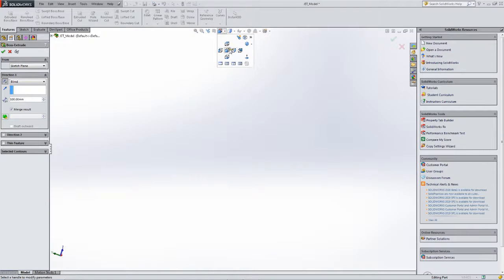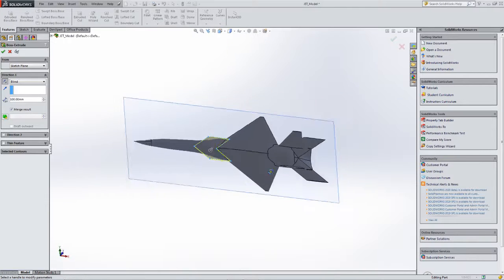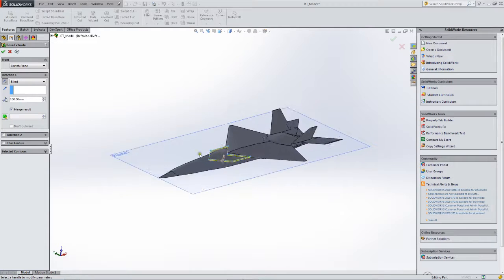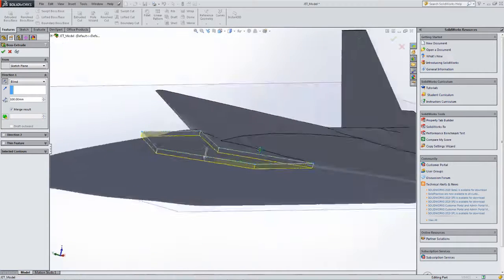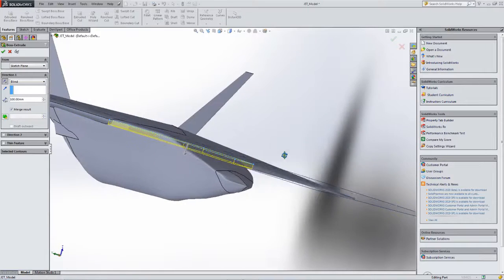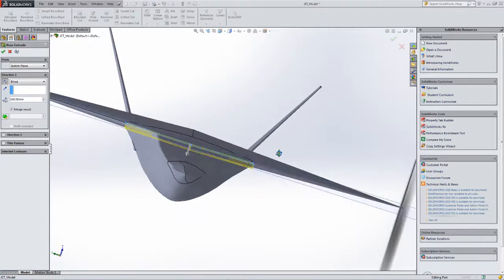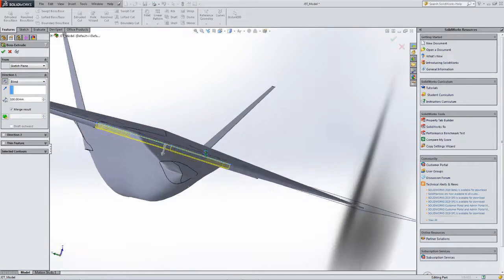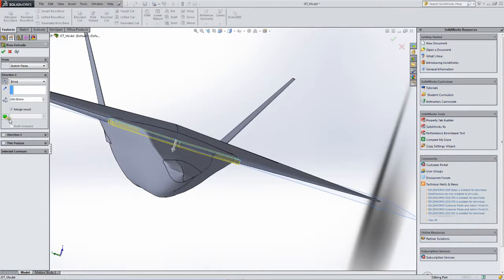So that's good. 10 millimeters is, oh, there I did it again. Whenever I do that, I just go back to one of the standard views up there, and then I can find it again. So that's probably thick enough, but it wouldn't be the way the top of an inlet would be shaped. But I'm going to get that shape by drafting inward. So look what happens. That's 1 degree. Let's go 1,000 millimeters, a meter, so you can really see what's going on.